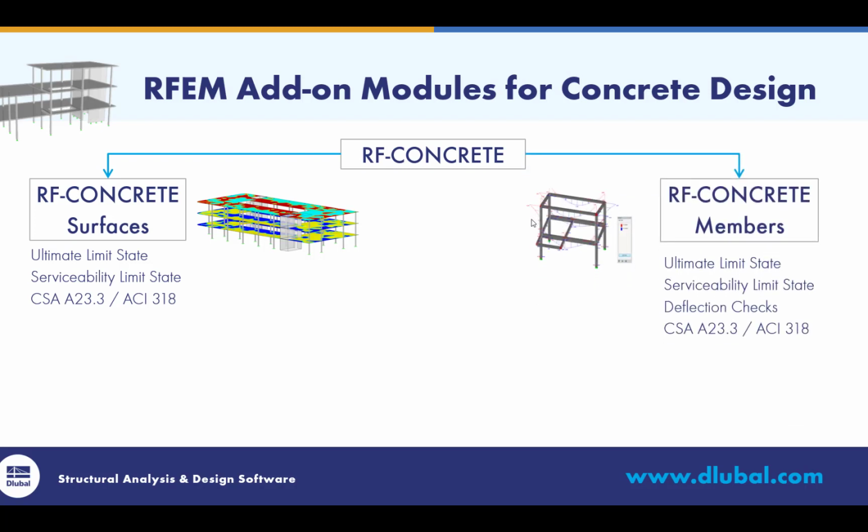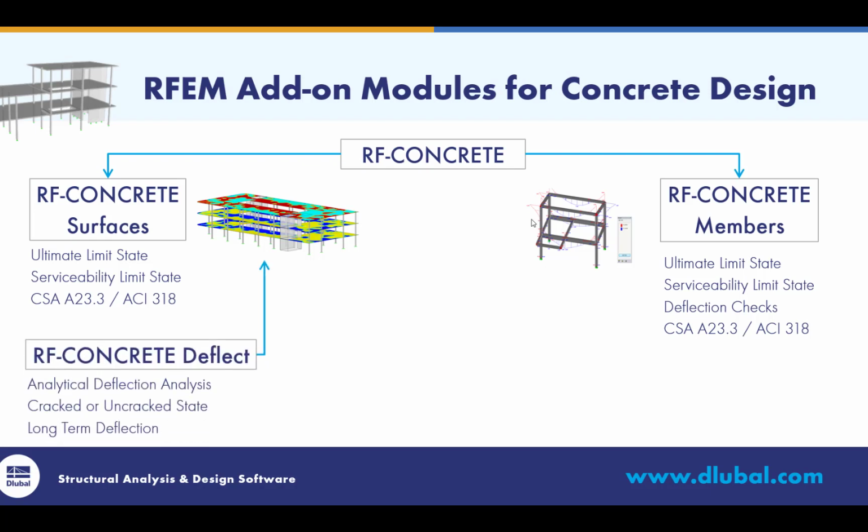The second is RF Concrete Members. Same concept. We can provide the ultimate and the serviceability limit state design for members, so beams or columns. We also can do a deflection check within this add-on module, again, per the CSA standard, but many other international standards available to us.